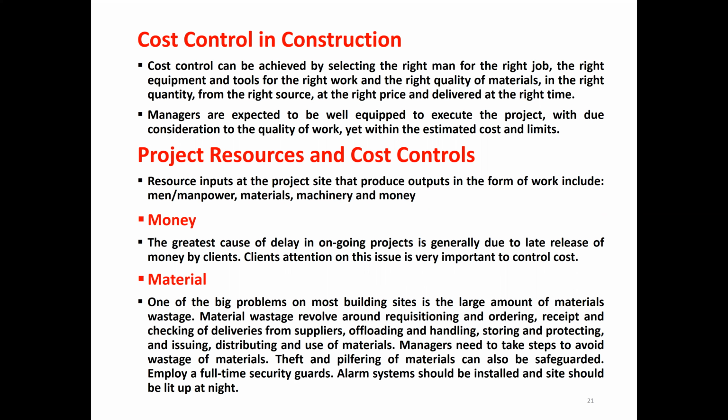Then material is very important. One of the big problems on most building sites is the large amount of material wastage. There is a lot of wastage. Material wastage revolves around requisitioning and ordering, when we order the material and when we receive the material, or checking of deliveries from the supplier.